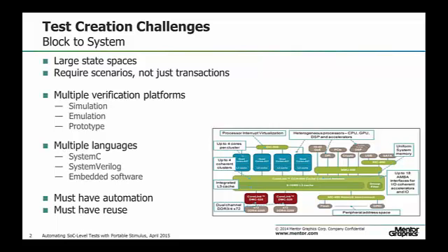Most of our users designing SoCs today don't use simulation alone. Typically we see usage of different verification platforms along the flow. People start maybe using something like SystemC for early prototyping. They move on to traditional RTL simulation, emulation, prototyping, and even post-silicon verification. The verification environment has to address all these different phases.